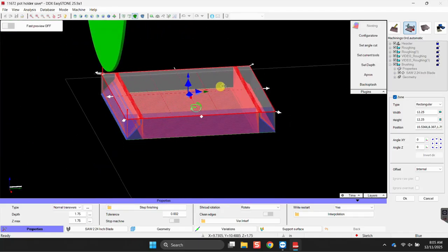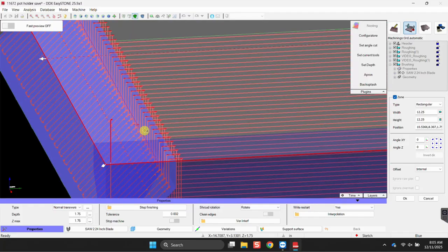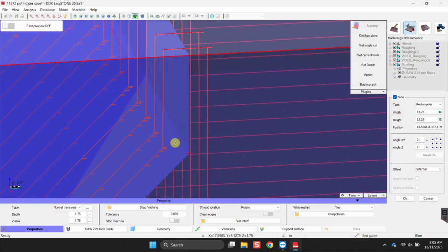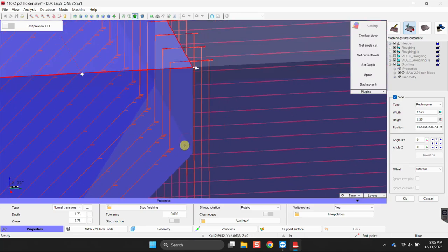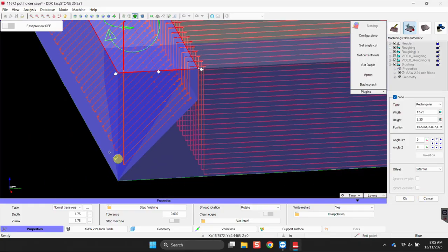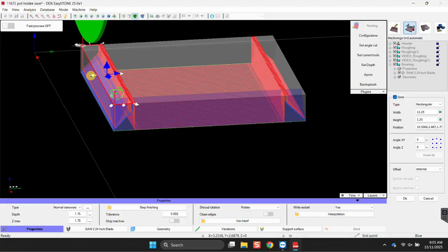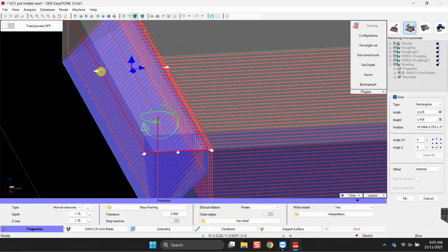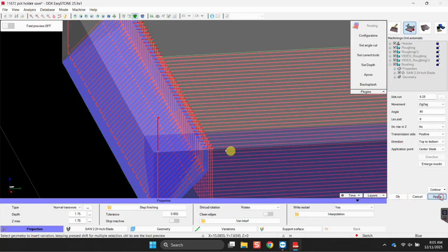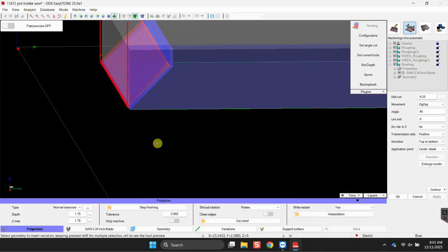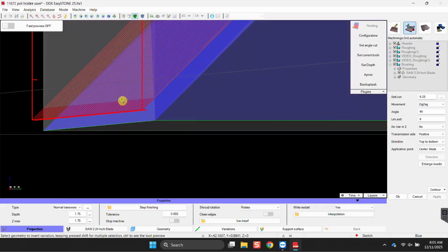So I clicked on that white arrow, and now I'm dragging it where I want it to apply to. I'm going to right click, use endpoint, and pick the corner here, this little intersection, to see if I can keep it up off the face and apply right here. And let's bring this one out just a touch. Let's right click, go to sketch, bring that out, and click OK and apply. Oh, did I hit apply? Yep, there we go.